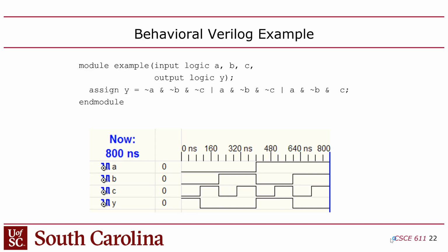And we're going to talk about that later in the class when I talk about logic delay, propagation delay, and contamination delay. But for now, when you run this in the simulator, this is a behavioral simulation only, it's technology agnostic. So it doesn't know what the propagation delay is because that all depends on the technology that you're using to implement this. In other words, how fast the FPGA is or how fast the technology node is when you fabricate this on an ASIC, like if it's a 4 nanometer process or an 11 nanometer process.